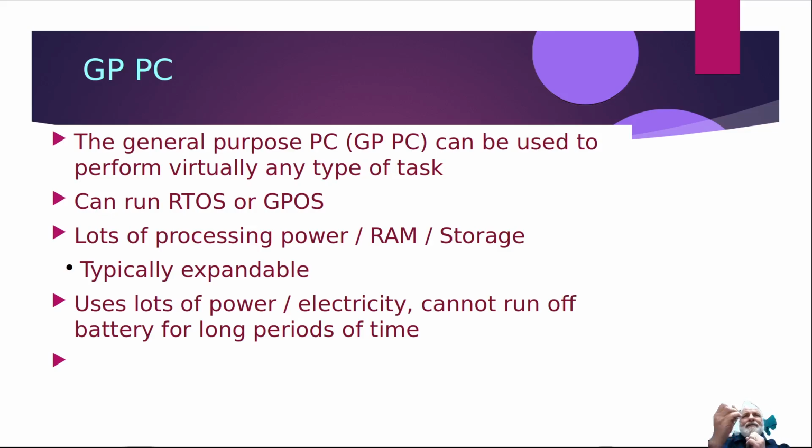So you can say, look, this task, again, if you think about the antifreeze coming out of the tank, you can dedicate and say, this particular task is very important. It needs to be done regularly, and I need to check the sensor and make sure that the sensor is telling me that the tank is not full, or when the sensor is full, I get that message within a few milliseconds, and then I get my message out to the pump and turn the pump off without any delays.